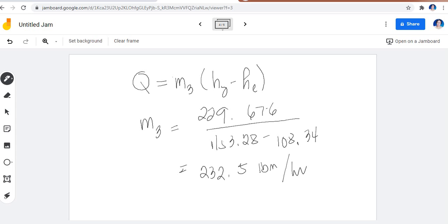A part of that steam, since it's going to liberate its energy content, will be condensed. As you can see here, there's a condensed part, this is your liquid and this is your vapor. So there's a change in phase for your steam. This is the energy content of that steam, the same energy content that your air-water vapor mixture is going to receive.